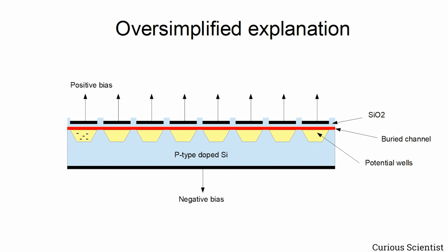And then out of these two, let's call them particles, the negative charge, the electrons, is captured. And the capturing happens in potential wells which are created inside this CCD sensor. And what is happening is that this accumulated charge, which is proportional to the incident light, is just accumulated.